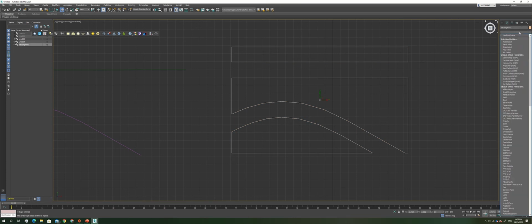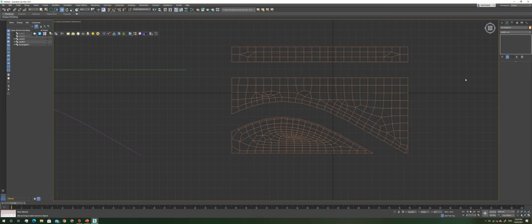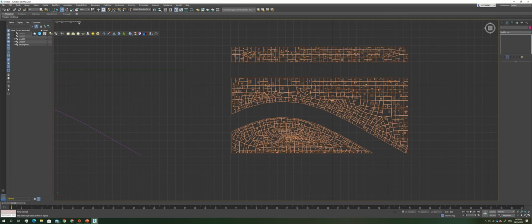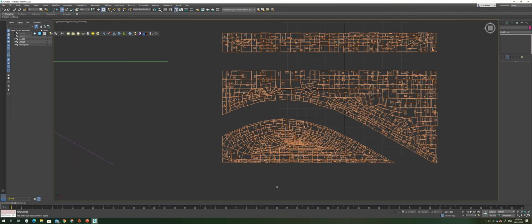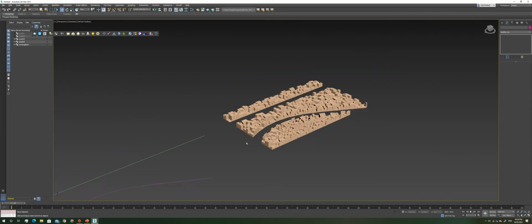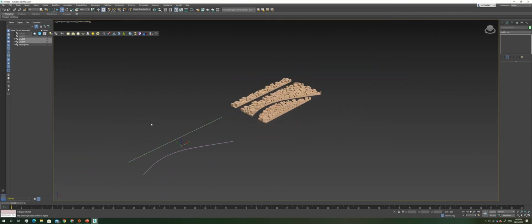Next, select the shape, and in our Modifier tab, select Quantize Mesh. This will divide up our shape into a grid. Next, in the Modifiers, select Greeble. Now we have a randomly generated city block. In our viewport, turn it to perspective so we can get a better view. Shading to default shading. Now we can move our copied lines into the spaces of our newly created paths.